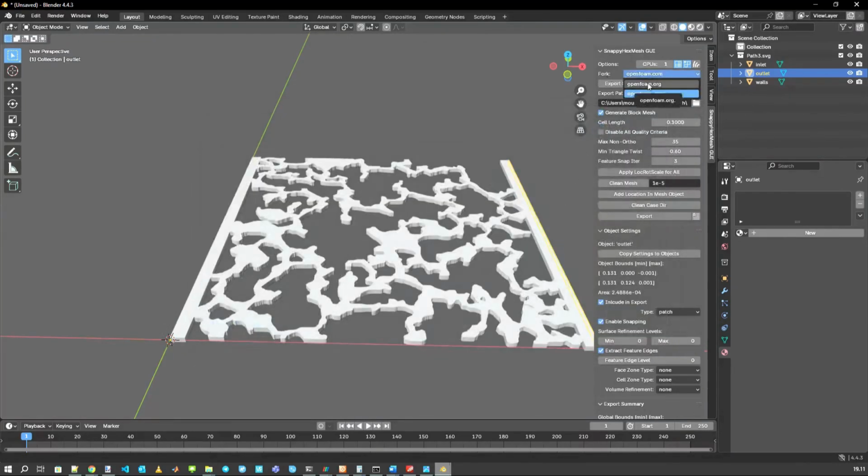First select the OpenFOAM version. I use OpenFOAM 12, so it's from openfoam.org. You can select the number of CPUs, also the castellation phase, which is an option in snappyHexMesh, and the snapping phase, and also the boundary layer phase. I do not select the boundary layer phase right now because it is not that important in my geometry.